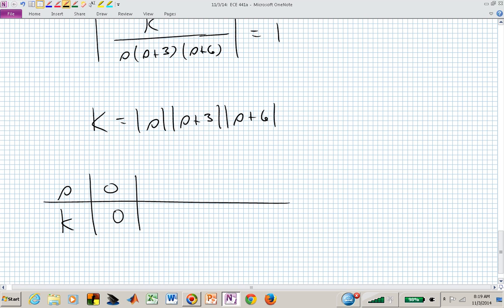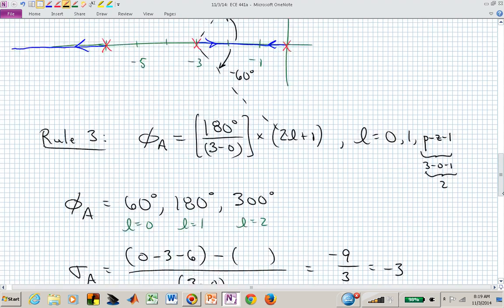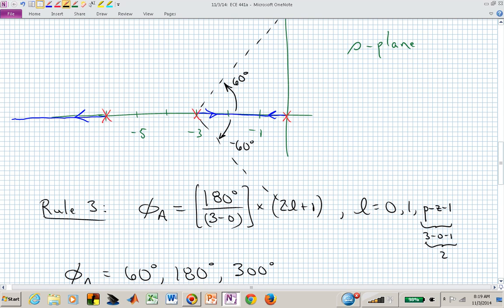And now you might just say, well, just for sanity check, it better be 0 at minus 3, right? And it is. We're really interested in what's the value of gain K between 0 and minus 3, just to show you that it's not symmetric as far as how these branches approach each other. They don't come together uniformly necessarily as you increase K. Meaning the one at the origin may go over to minus 1/2, and the one at minus 3 may get closer or not so close relative to that 1/2 distance.